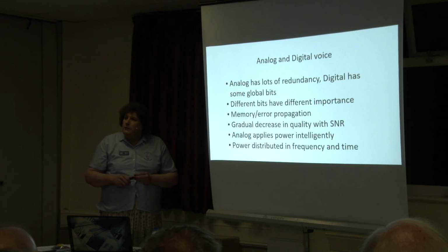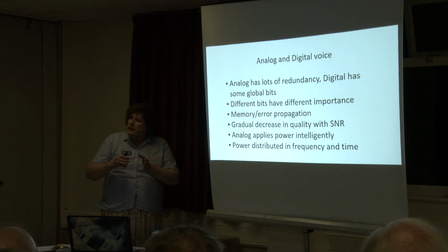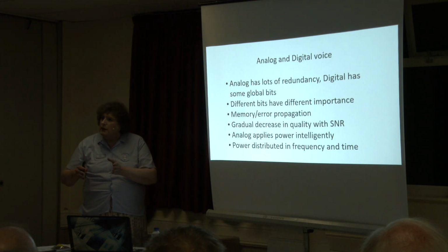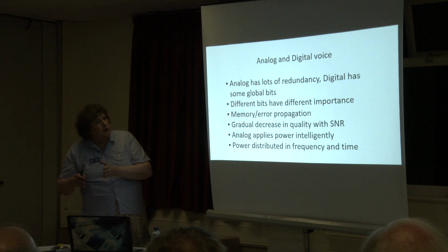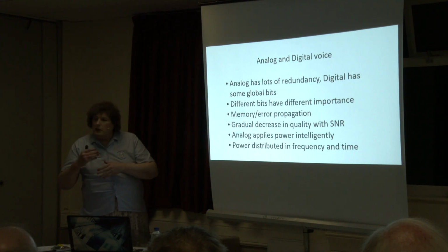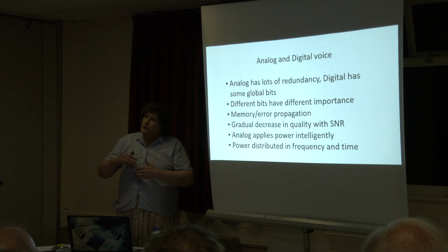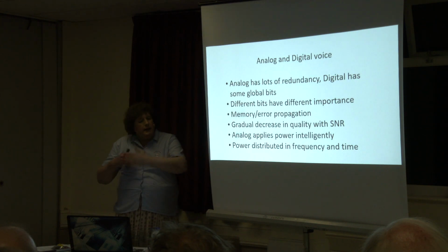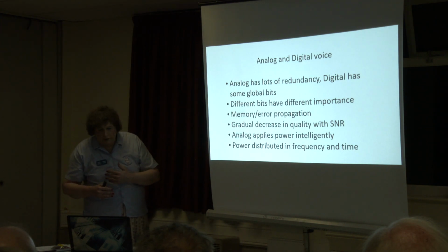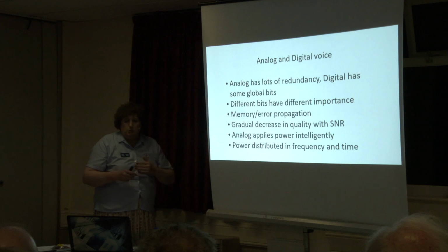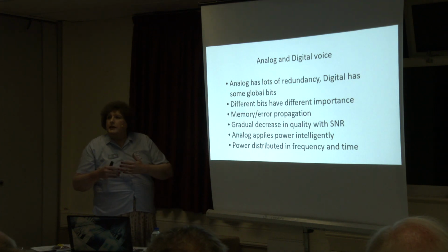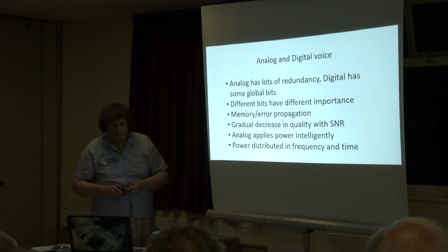So if it misses one bit, it will miss the second bit, and then it will effectively resync again. So that's the memory part, where it misses the first bit, misses the second, and then basically will resync on the third. So that's where it helps sort of correct its errors, so to speak.